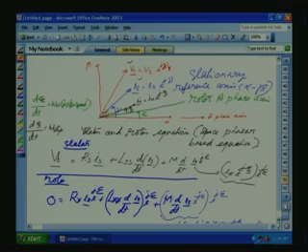this gamma here. Now because of the relative motion of the stator and the rotor, there is a flux generated. The rotor will have a rotor current, and we know that previously we studied the rotor current frequency will be proportional to the slip frequency.